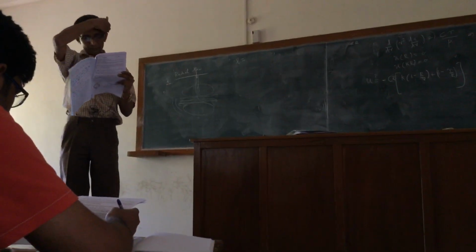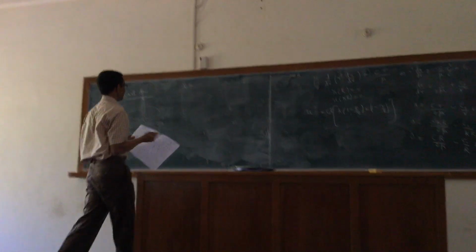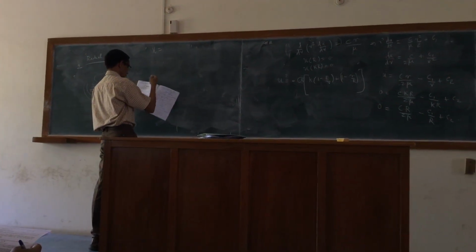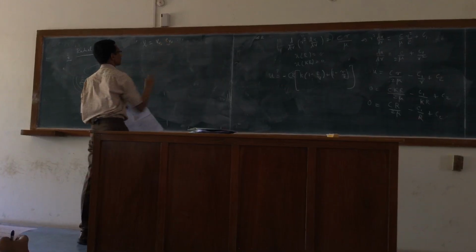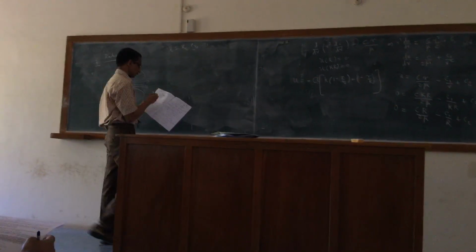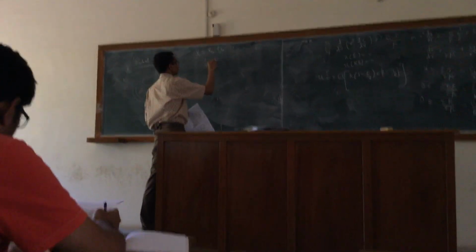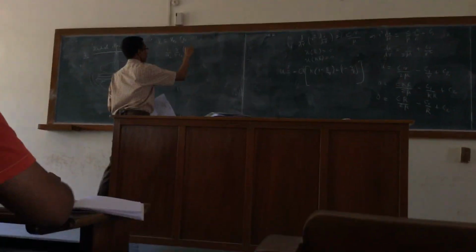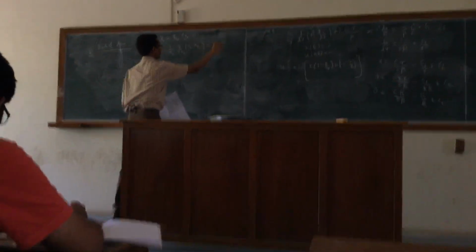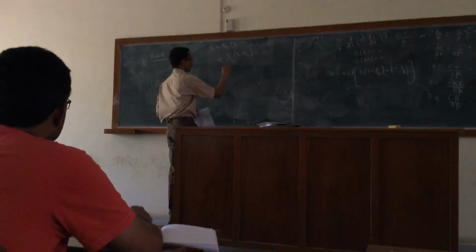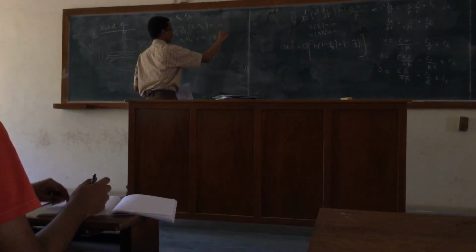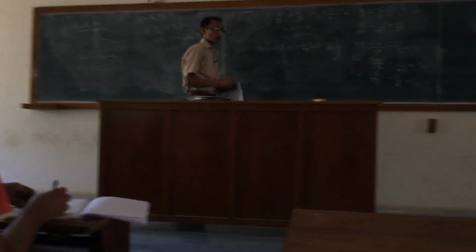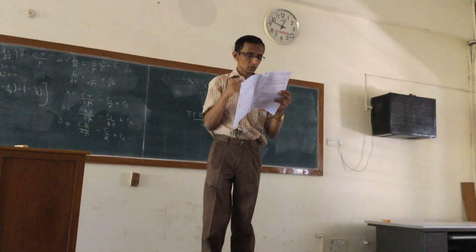And again, there are a lot of assumptions that are not there in the problem statement, and even though I modified the problem statement, I still haven't given them, so that's why I'm discussing this. So now the continuity equation would be equal to 0. What this means is that r times v_r is a function of phi and z. Again, you have to really solve the problem. To get to the answer, you have to neglect the dependence on phi.